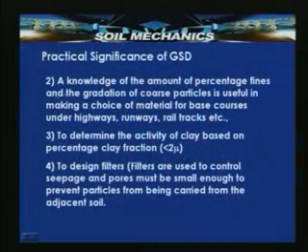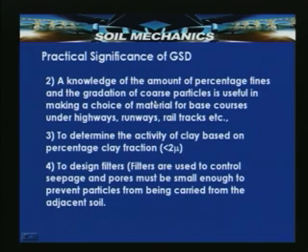The second significance: a knowledge of the percentage of fines and the gradation of the coarse particles is useful in making a choice of material for base materials under highways, runways and rail tracks. Basically, in highways and runways it is an utmost requirement to give a mechanically stable foundation to support the loads coming onto the pavement. So, for that we are required to have the matrix with a certain amount of fines.